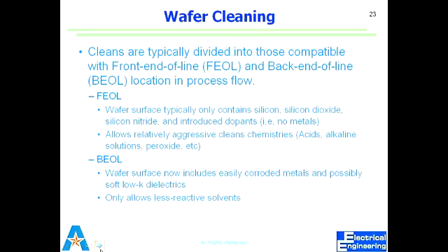Before I go into these much more involved processes, solvent clean is a simple process which gets rid of many basic organic materials. I can use solvent clean on wafers as well. It's relatively a less harsh cleaning. And when I use acids in any type of cleaning, those are harsh treatments. So if I have devices which are very small, maybe I have some metal deposited which is 10 nanometers wide, I want to stay with solvent clean. I don't want to do acid treatment there. So it will depend on your judgment, what kind of cleaning you want to do.